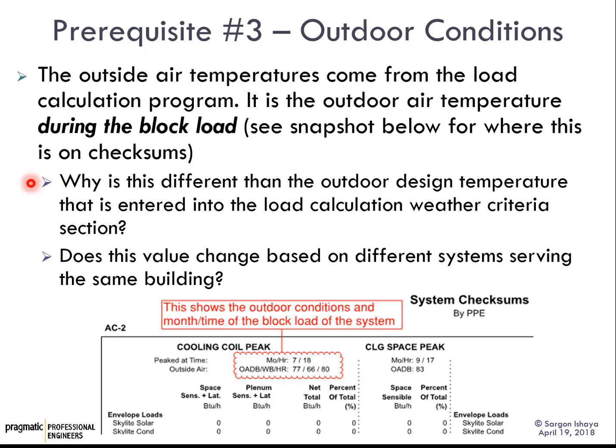So even though it's very warm outside, it takes a few hours for the heat to impinge on the outdoor concrete of the building before it actually gets into the space. It takes time for that heat to travel through the concrete, and that time can be several hours.